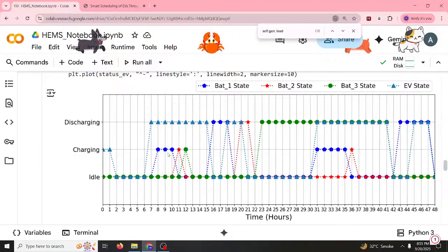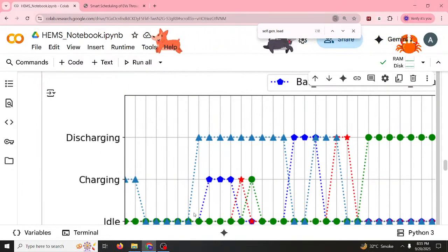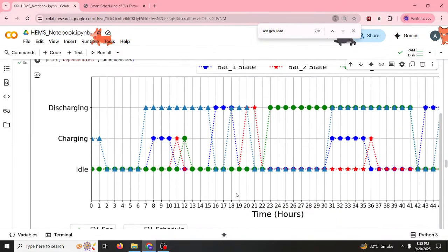Here we see these battery states. Battery states are either charging, discharging, or idle. So these three states are given here. Clearly, we can see in the time frame that sometimes it is first charging, then goes to idle. So we can go from idle to charging and idle to discharging, but not from charging to discharging directly. You will not see any jump from charging to discharging here. Rather, you will see the jumps from idle to charging or idle to discharging like this.